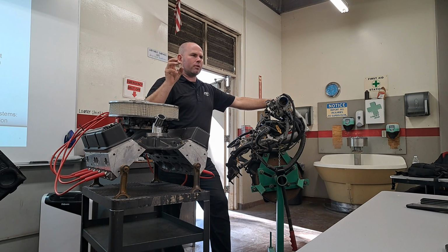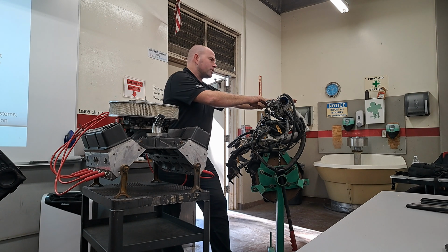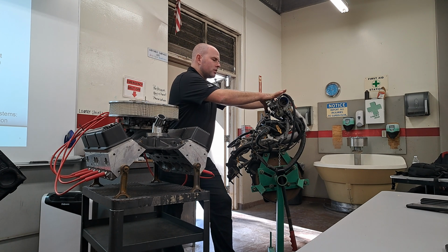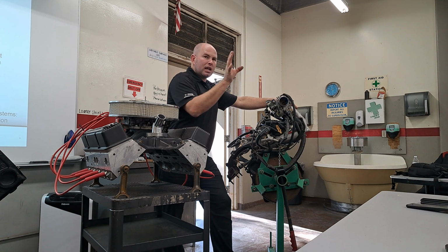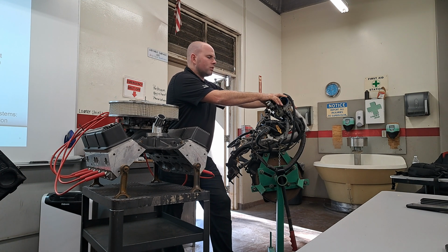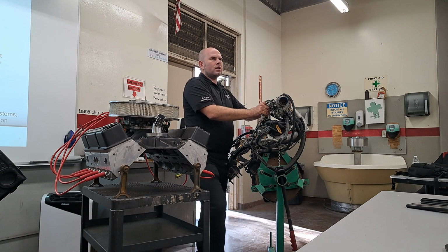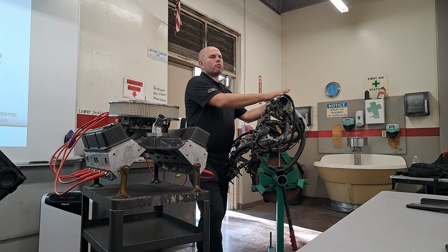Now there's an accelerator pedal position sensor, and roughly that controls this, but that gives the computer the ability to ultimately have control. So the cable-less system would be drive-by-wire. You're using a wire, not a cable. There are quite a few reasons for that. They actually can control the throttle better than you can for emissions and stuff like that.